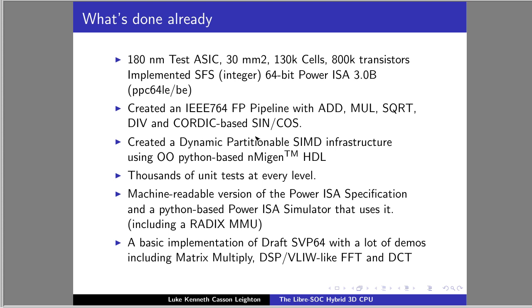The typical way that you would do SIMD would be a for loop, an if statement. If you want 1 times 64, then do this HDL. Else, if you want 2 times 32, then do literally a for loop in your HDL around two different adds.